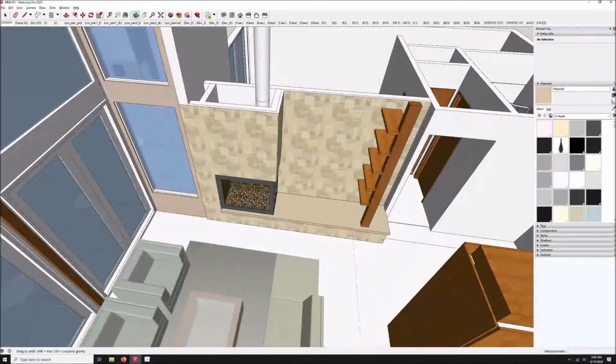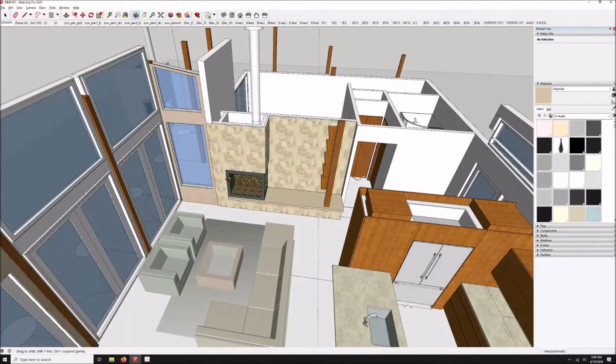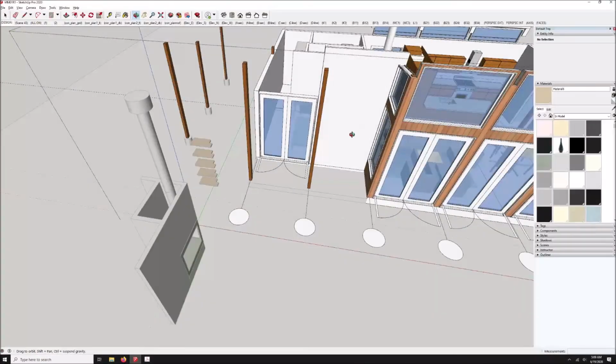Now with this kind of fireplace, I have an option. I have choices as far as how to vent it. I could just vent straight out the side, or I could vent up and out, or straight up. My initial thought was to vent out the side, but then that means the vent is coming out right here, and the vents get very hot, so you don't want to have them in an area where people could easily brush up against them.